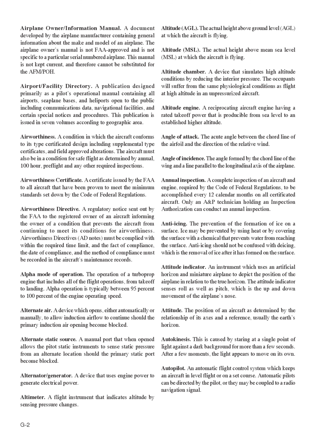Alternate air. A device which opens, either automatically or manually, to allow induction airflow to continue should the primary induction air opening become blocked. Attitude. The position of an aircraft is determined by the relationship of its axis and a reference, usually the Earth's horizon. Alternate static source. A manual port that when opened allows the pitot-static instruments to send static pressure from an alternate location should the primary static port become blocked.